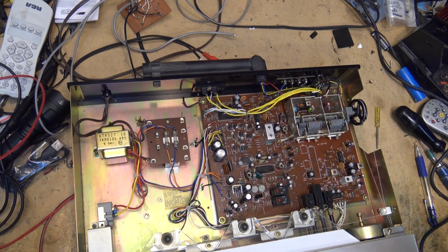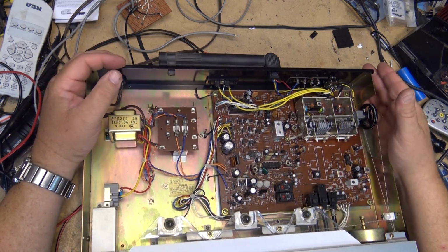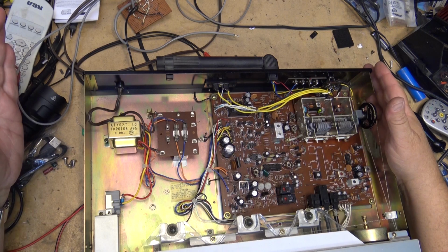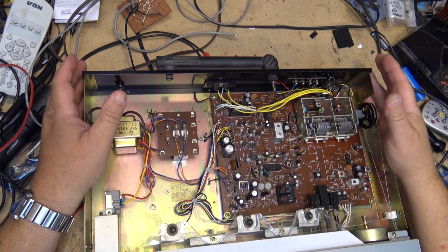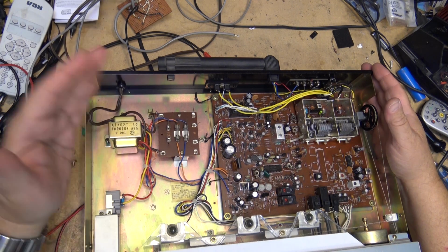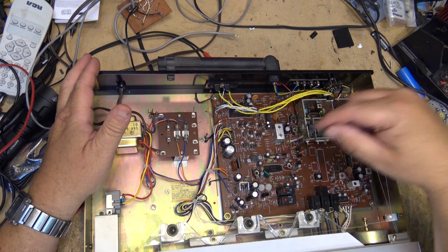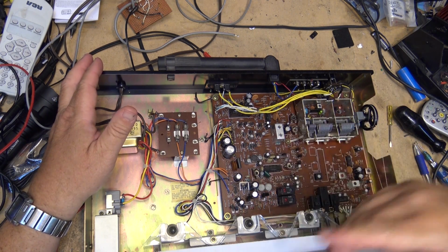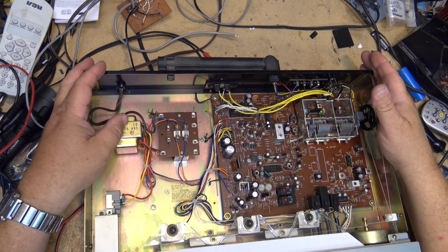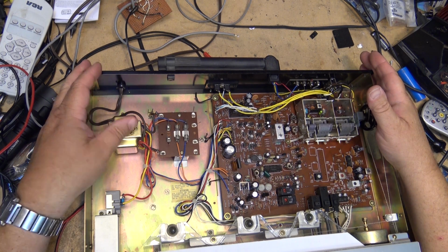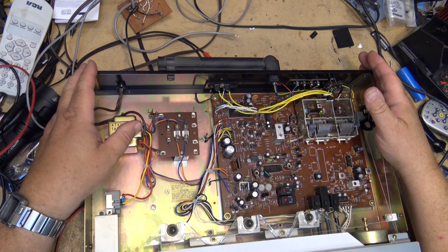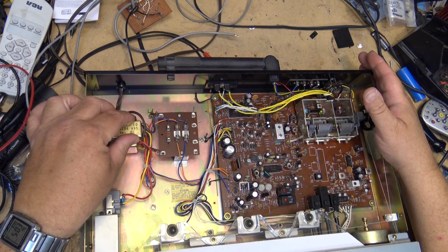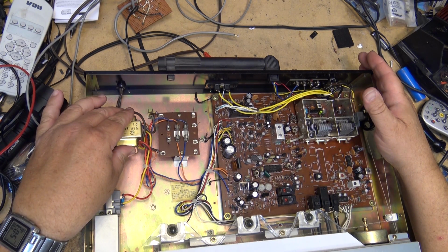But anyway, I figured I'd show you guys SCA, how it works. Yes, it's still in operation after all these years. I didn't expect to actually pick up anything with it, but the easiest way obviously is just to take your detector output and just plug it into a shortwave radio that can tune down to 67 kilohertz. That's the easiest way to do it, and actually you get the best quality because you're getting a much better receiver that's able to tune that signal in.